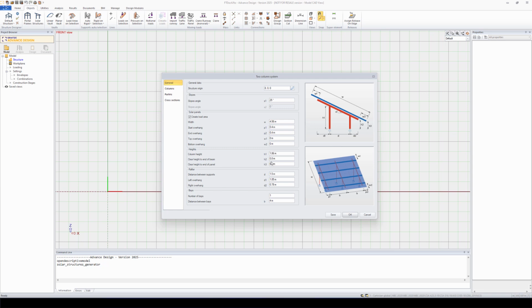As I mentioned earlier, it's going to automatically adjust the parameters. For the rafters, I'm going to use 2.5 meters. Just to let you know, in this scenario, I am using metric units, but you can also change the units in Advanced Design to imperial. It's very simple. You just double click here, and then you can switch all of the units to imperial units. Again, after I put this in, it's going to automatically calculate the other D1 and D2 spaces, or the dimensions there.